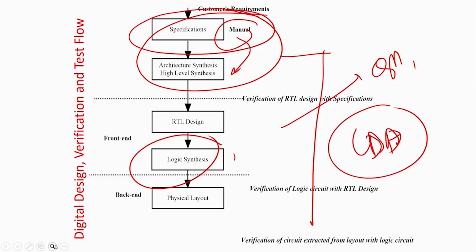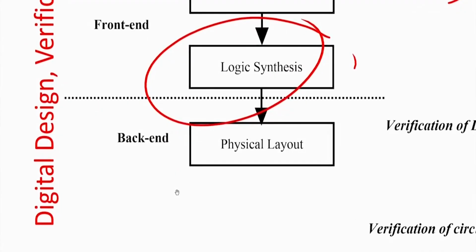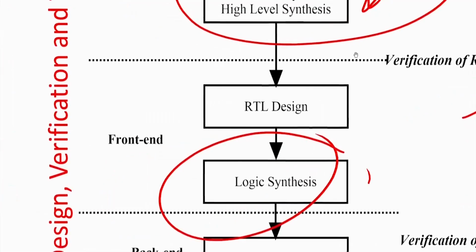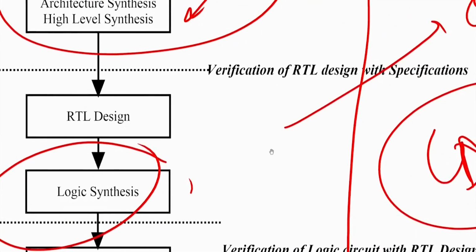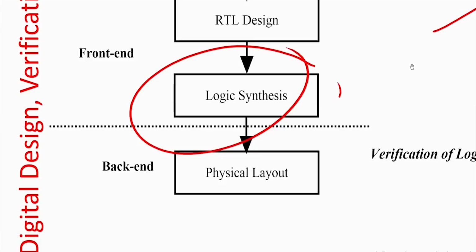Similarly, all these optimizations will be discussed, but the only thing is that after this first dotted line, it is based on the optimization of the CAD tool, not on the input side. It is on the CAD tool which automatically synthesizes the circuit for you. So we will have good algorithms so that you can synthesize a very good quality circuit in a very short amount of time, because Quine-McCluskey and Karnaugh maps can also solve the problem, but they will take years to design a circuit, whereas heuristics like Espresso will do it very quickly.